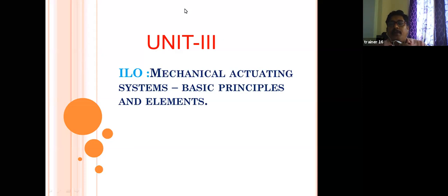In control of a double acting cylinder, we used a solenoid 5 by 2 valve. That means it has 5 ports and 2 positions, and it is changing positions. That is also the same in the mechatronics lab, the same experiment list.